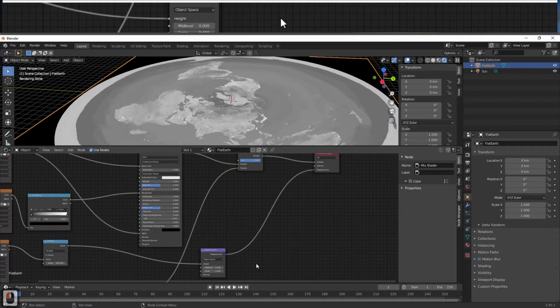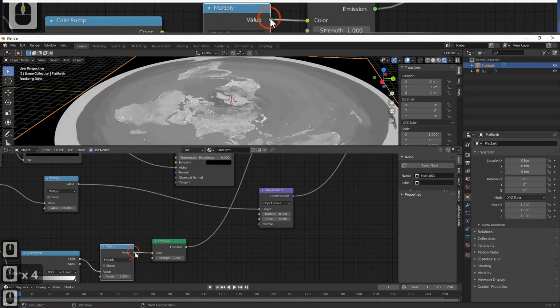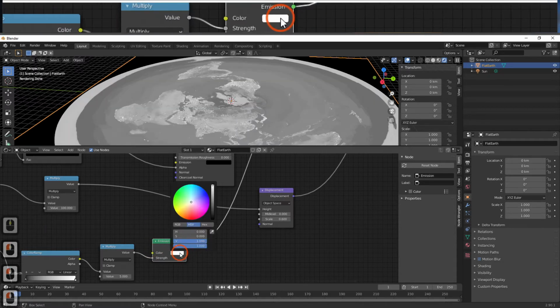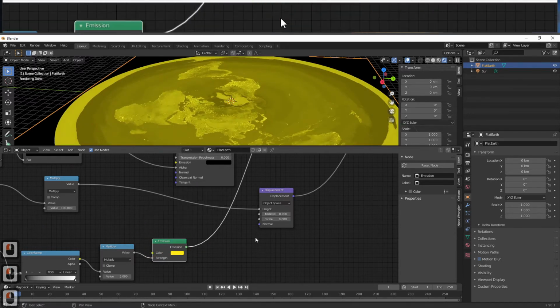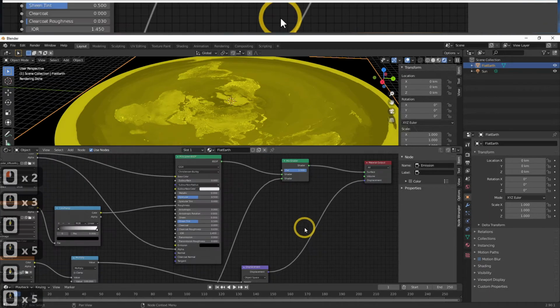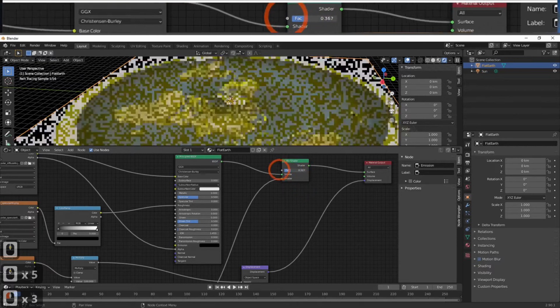This mix shader, as the name implies, mixes two shader values based on FAC. Now, if those two nodes were the other way around, just reconnect one and the existing one would swap. Our emission output will be the bottom shader input node in mix shader.